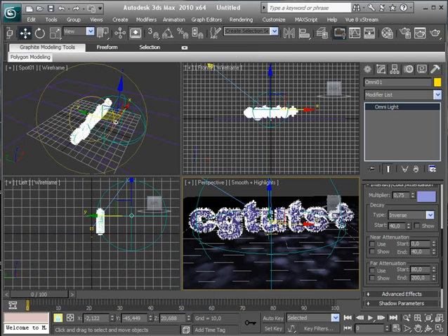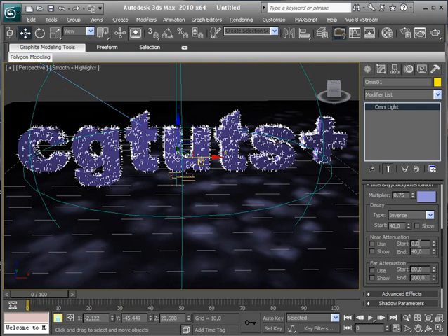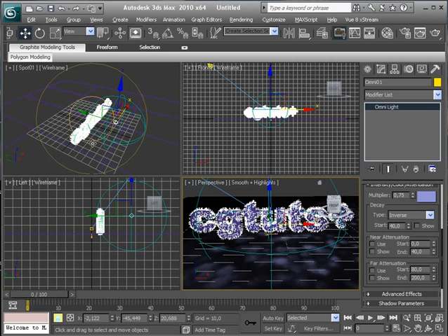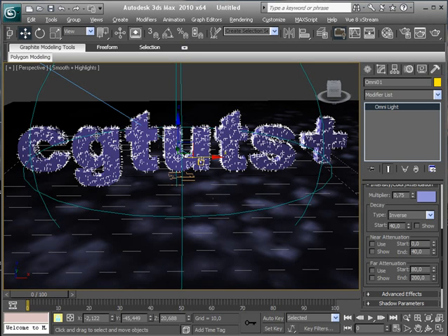If we have our particles here, I'm gonna zoom in. I just pressed Alt and W, that maximizes our viewport. So if we scrub through the timeline, you'll see that although I introduced the delete operator, nothing is happening. That's because we have only 100 frames and we need to introduce a little bit more.